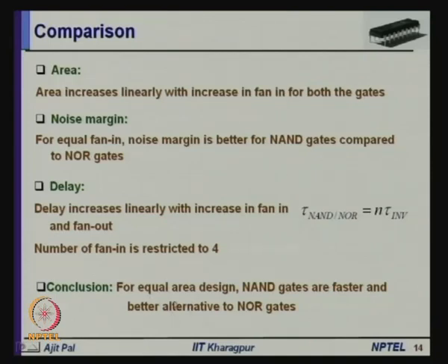So, what is the conclusion? The conclusion is that for equal area design, NAND gates are faster and a better alternative to NOR gates. This is the conclusion that we can make from the comparison of area, noise margin, delay and other parameters.